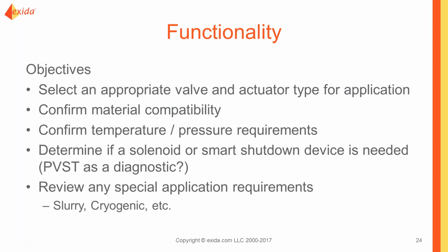So functionality, objectives: we want to select a valve and actuator or a motor or a pump that's applicable for our situation. Confirm material compatibility, confirm pressure and temperature requirements, and as I was talking about, are there any special requirements for diagnostics? Do you need a smart shutdown device to run partial valve stroke testing, or are you going to do an application type diagnostic such as a partial valve stroke test controlled by the safety instrumented system?